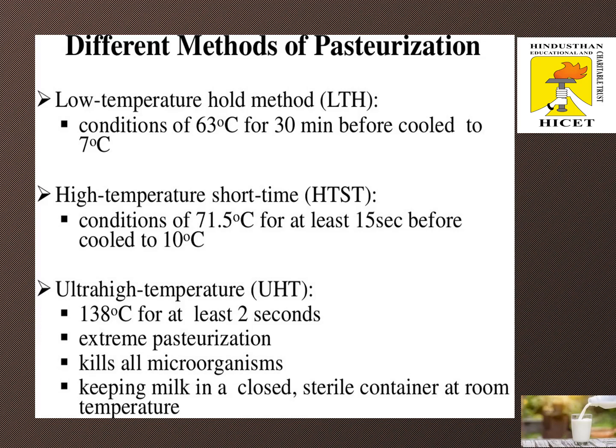So the industry people are using HTST as the optimum pasteurization technique for the preservation of milk. The reason is that in LTLT you are treating the milk at 60 degrees Celsius for 30 minutes. When the product is exposed to higher temperature for a longer time, the quality and the nutritional properties get minimized. Even though the shelf life of the milk increases, we are receiving a lower quality product. That's why people go for HTST. We are only exposing the milk for 15 seconds.